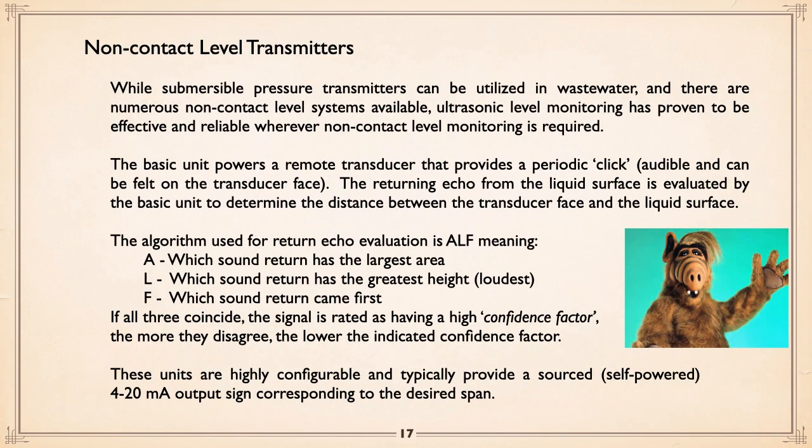Now, level transmitters. If we're not using submersible transmitters, which you can use in wastewater, there's all sorts of non-contact types, there's ultrasonic and so on. My own personal preference for non-contact has been to use audible, in other words, ultrasonic, call it what you want.